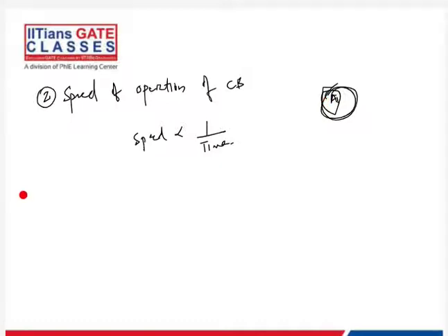Then we can always install good governors. We always assume that PS is constant. So here we are trying to play with the assumptions. If we have a really good governor, then when the fault occurs, PS also can be reduced.